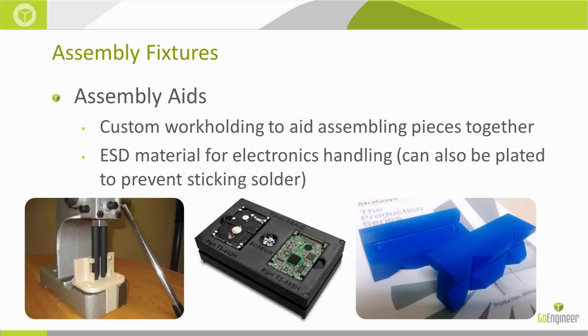So you have to assemble these hoses yourself, and it takes quite a bit of force and torque to stick these end fittings on these hoses. They're also meant to be kind of decorative, and like I said, they're anodized aluminum, so they're quite soft. So companies will sell specialized aluminum soft jaws, shaped exactly like what I have here, and also aluminum wrenches to help you put these parts together without scratching them. And I have the printers here, and I use them as I can.